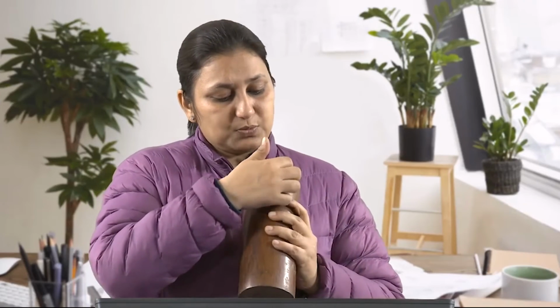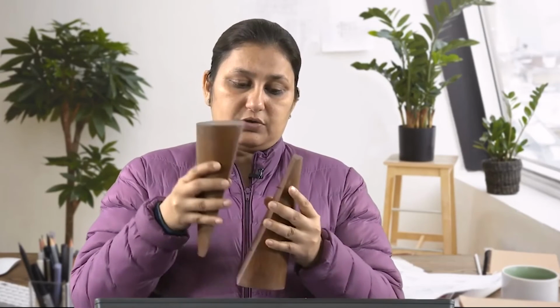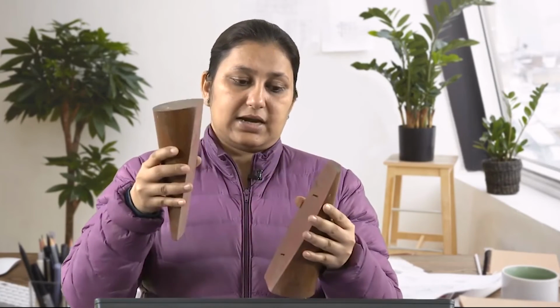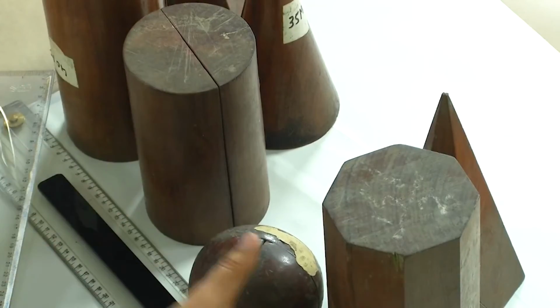This was dependent upon how the section plane. So, if you look at this, the section plane was passing through the top base and the bottom base both. So, we have both the top bases and the bottom bases being cut, and that is why this peculiar shape. In this case, this was perpendicular to the base. So, what we got was a simple rectangle. That is how the section of cylinders are going to be.